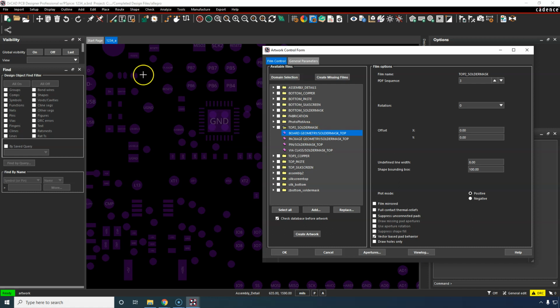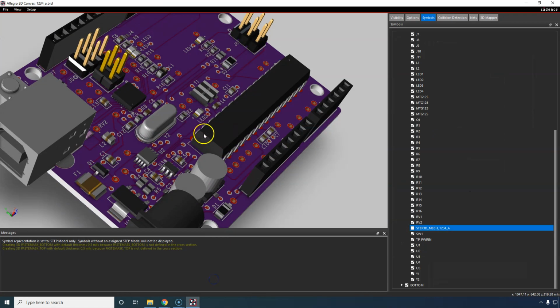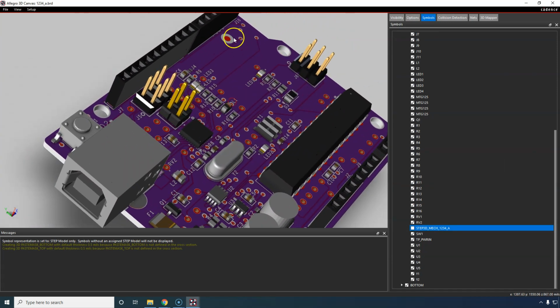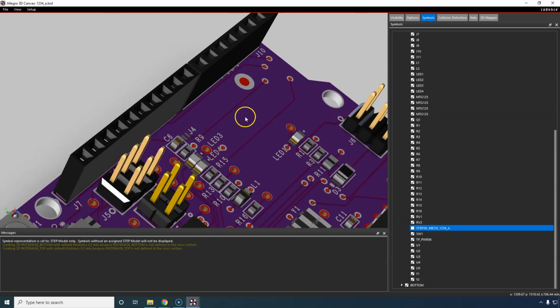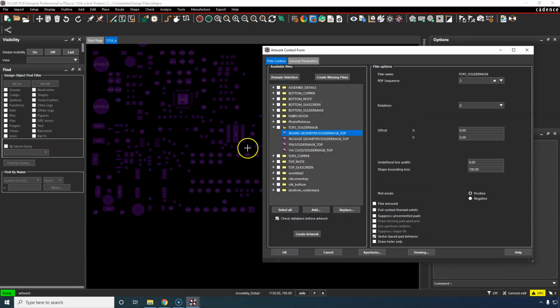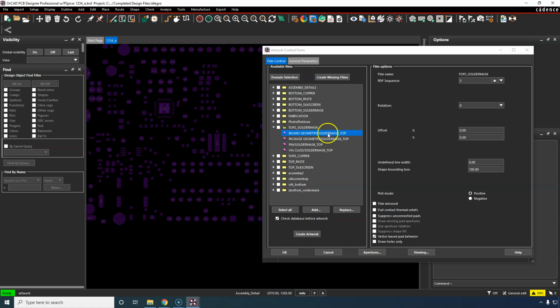And then we have the solder mask top for the board geometry. Well, what is this? This is specific to the board. If there's anywhere on the board where we just want to expose some copper, just somewhere, willy-nilly, we can find somewhere on the board geometry where we want to draw a shape in the solder mask subclass of this board geometry class. We draw a shape and say, hey, we want to expose this area because we want to see the copper, because, you know, we're weird like that. And then that's what you see. That's what you do.